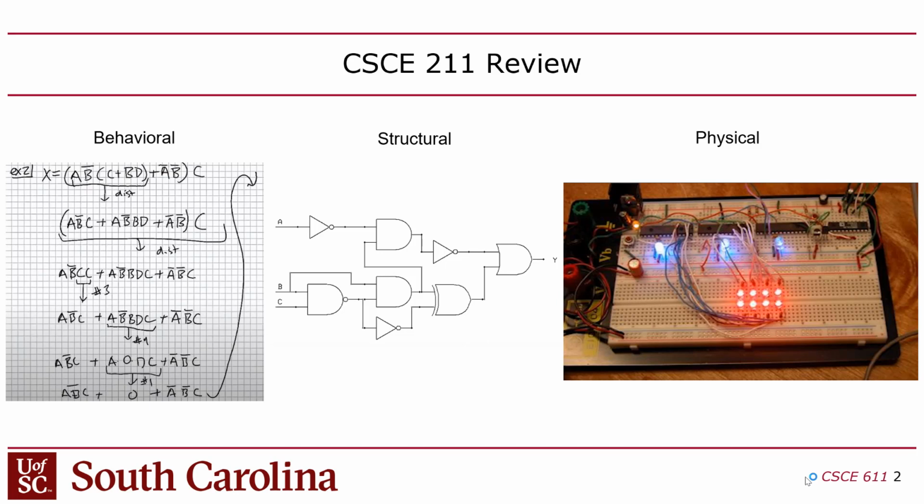The schematic, or the Boolean algebra here, is called the behavioral representation of the circuit because it defines the functionality, the behavior of what the circuit is supposed to be doing. The schematic is the structural representation, which is when you have components or modules that are selected from some kind of a repertoire, a menu of modules that you have in a library of some kind, and that you can logically instance in a schematic, and then connect together with wires.